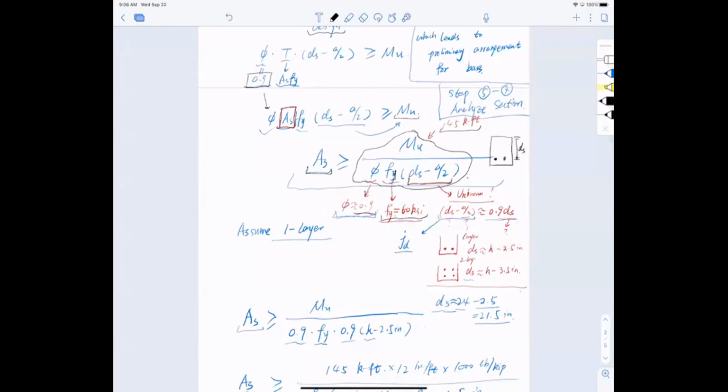The other unknown is the effective compressive zone size, a. Why is that? Because we don't have reinforcement, we don't know how much concrete it would take to balance out the tension forces. So these two are unknown, and with these two unknown, we don't know the distance between the center of the compression force and the center of the tension force. So the lever arm jd is unknown.